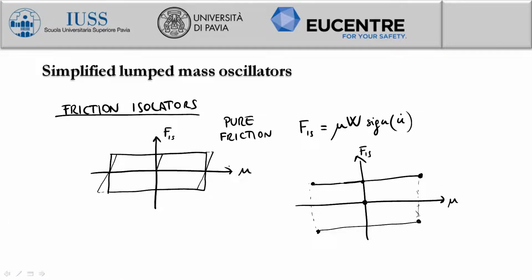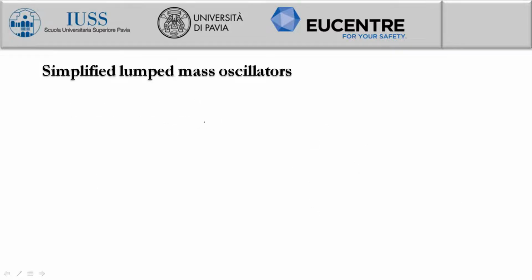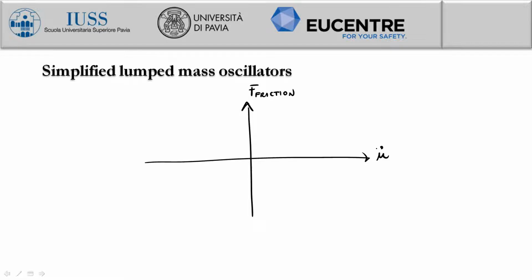So according to this definition, we can have the frictional force with respect to the velocity. Okay, if we consider the sign, so the Coulomb's theory, we have just this. This is the graphical representation of the sign function. Okay, we have a gap at zero velocity. And this is the reason why when we have zero velocity, which is when we achieve maximum and minimum displacement, we don't have any values inside this transition branch. Okay, so this is the Coulomb's theory.